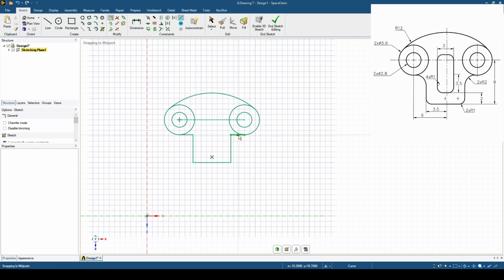And after that, I go to rounded corner. I will start from there to there, and it should be a radius of 2. So I click 2. Also there, the same, it should have 2 millimeter. The bottom one, they have a radius of 1 millimeter. So 1. And there we should have 1. So we are safe right now.